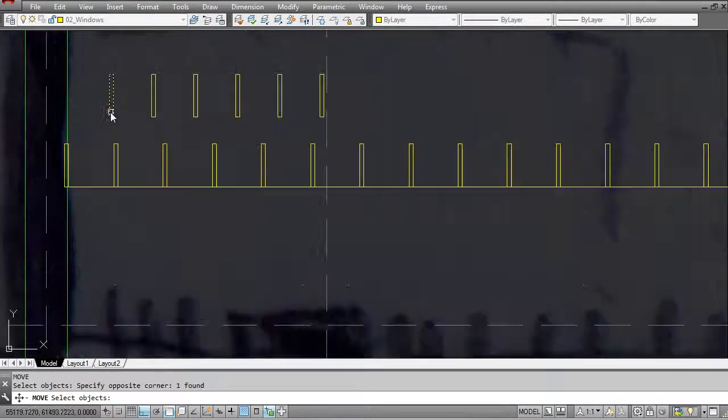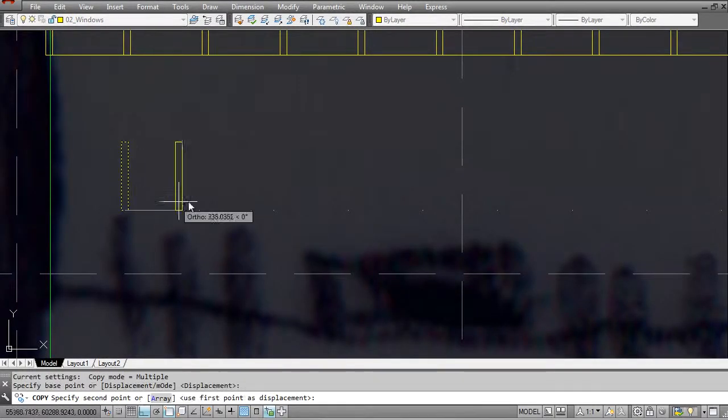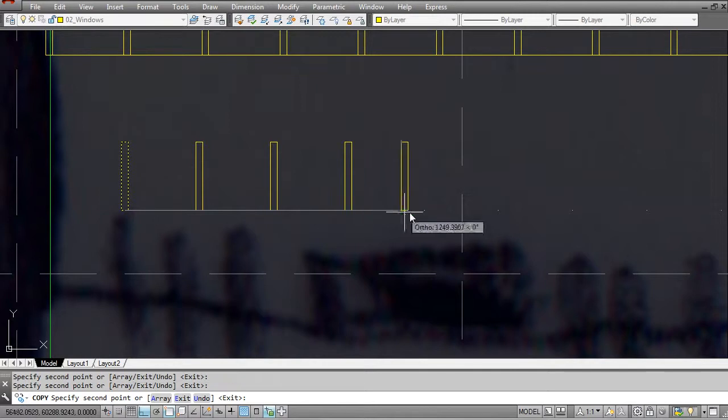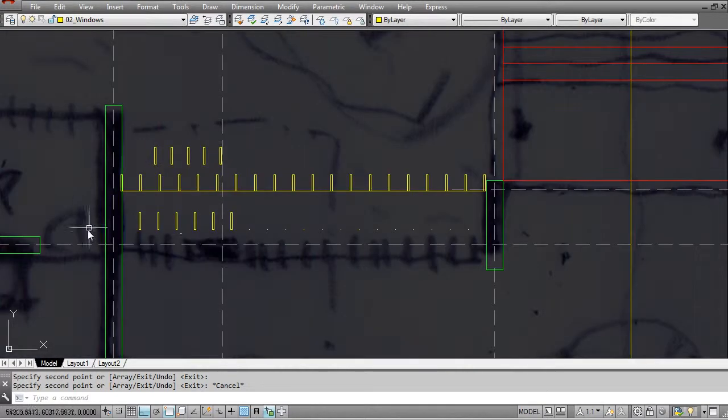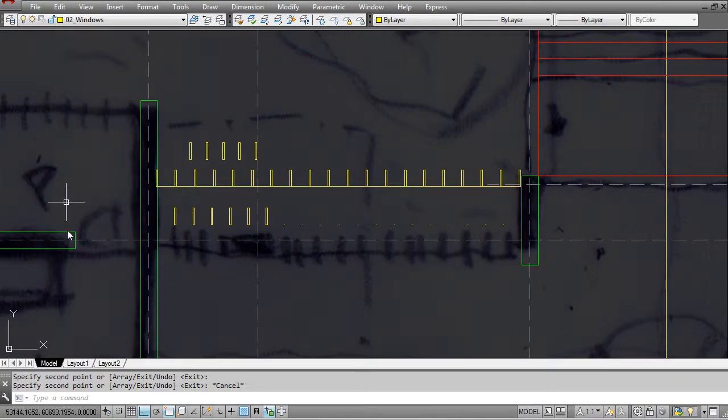So this is really helpful, as well as you can just keep those little points as very easy and efficient base points. So you can then just copy that across and then use those points as a base point to copy with. So this is something, if you have a distance and you don't know the distance in between the two, you just have a total distance and you know the total amount between that point, you can then use that divide method. So these three methods pretty much will cover the main creation methods for any type of screen or frame or any other small object that you want to copy at a precise interval. Either you know the interval, the spacing center to center, or you know the total distance and the total amount that you want to copy.